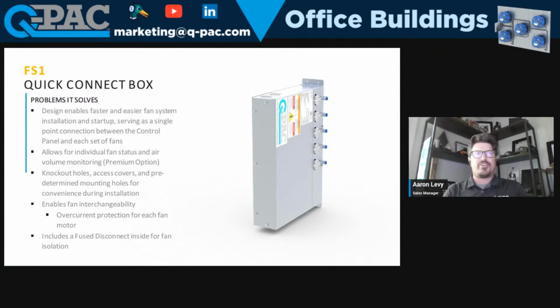So, it has overprotection. The fans themselves have protection as well, which I think we talk about next. And it also includes your pressure transducers in there for mounting on a premium controller for your high and low pressure. All of that stuff's inside that quick connect box.